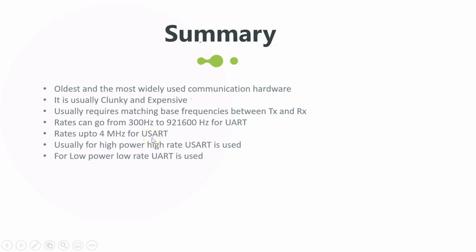UART generates its data clock internally to the microcontroller, and then synchronizes the clock with the data stream using the start bit transition that we saw a few slides back. There is no incoming clock signal to synchronize. A USART, on the other hand, can be set up to run in a synchronous mode. In this mode, the sending peripheral generates a clock that the receiving peripheral can recover from the data stream without knowing the baud rate ahead of time.